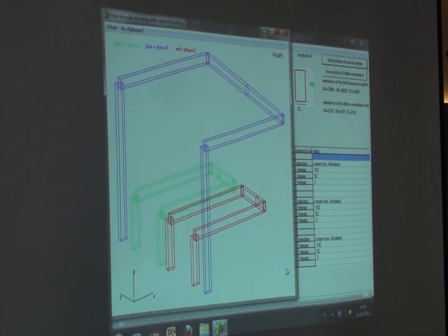E3 is EAC minus ECB. You see, if you have a symmetrical system in the star side, you must have a symmetrical current flow in the delta side. And you see that the currents in the delta are square root of 3 smaller than the currents in the star side. The transformer windings have a smaller current than in the furnace. Is that clear? Okay.